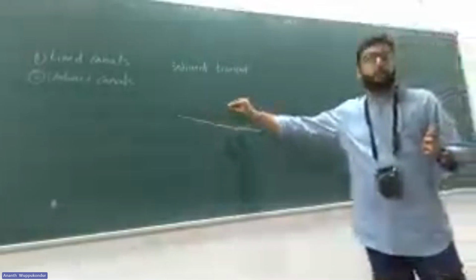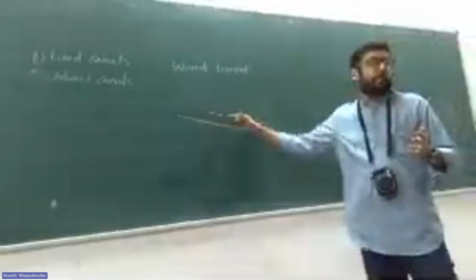And what about the maintenance cost? So if there is a continuous erosion and deposition happening, then you need to continuously monitor the channel and you need to make maintenance to make sure the bed is horizontal, not horizontal, but plane. So these are the problems with sediment transport. And to avoid these problems, we are going to see actually how the sediments start to move. And once we understand how the sediments is moving, then we will design a channel so that the sediments are not moving. So we are going to design an unlined canal today.